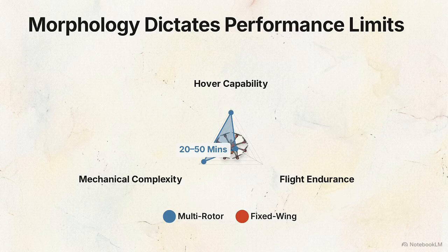However, maintaining lift through continuous motor rotation incurs a high energy cost. Consequently, the multi-rotor profile drops low on the endurance axis, with typical flight times limited to 20 to 50 minutes due to high power consumption.